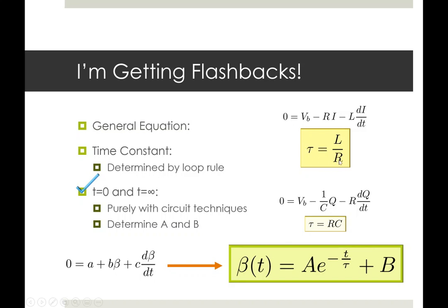Maybe more interesting is the fact that increasing the resistance actually decreases the time constant. What's going on there essentially is that you have less distance to go. When you increase the resistance, you don't have to go as far to build up to your max current, because increased resistance lowers what your maximum current is going to be, so therefore it feels like it's easier to get there in some sense. That's my loose conceptual argument for why increasing the resistance decreases the time constant.